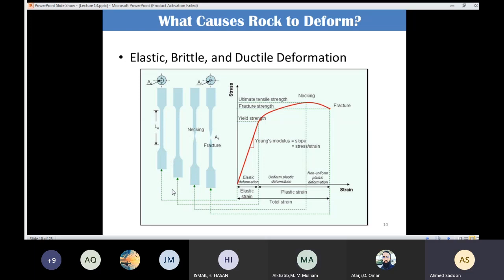We could have another possibility. Like what? The material will stay deformed? The material could stay deformed. It's the other possibility. So if I stretch a bar, then if I remove the force, I have two possibilities: either to get back to its original length, or I could have a new length. If I'm going to have a new length, that means I exceed the elastic region.